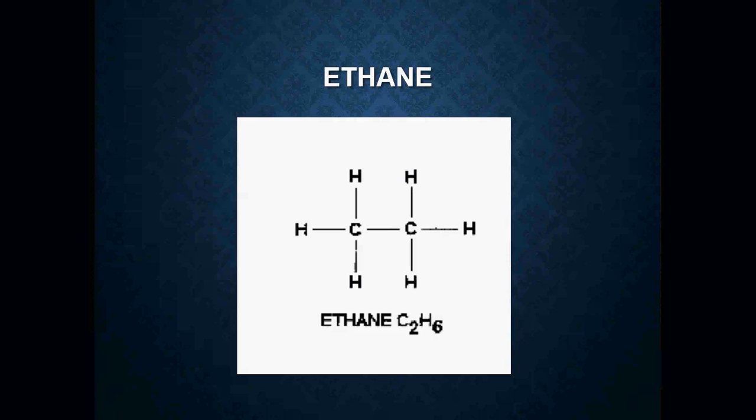Okay, so now, to understand combustion and to get things to burn correctly, we know that you have to have the combustion triangle. You got to have your heat, you got to have air, and you got to have a fuel. Well, in any of our gas-fired equipment, we have to have an ignition source, whether that's going to be a hot surface igniter, that's going to be a spark, that's going to be a standing pilot, whatever.